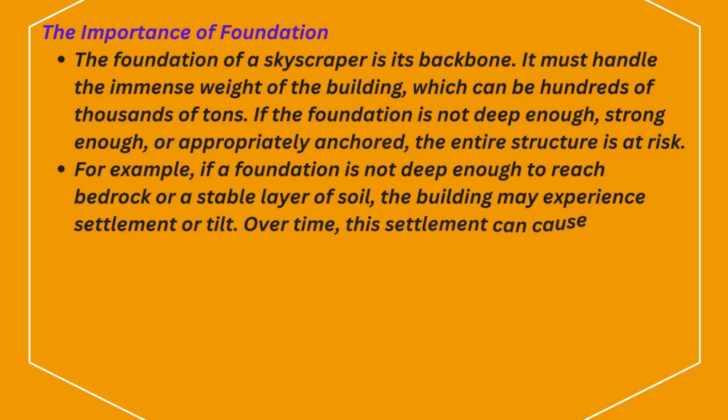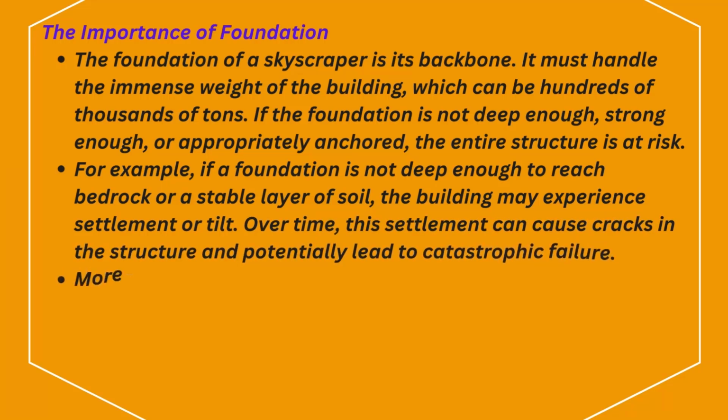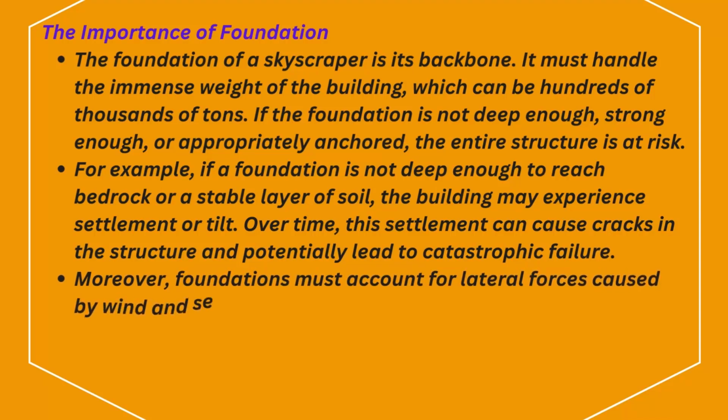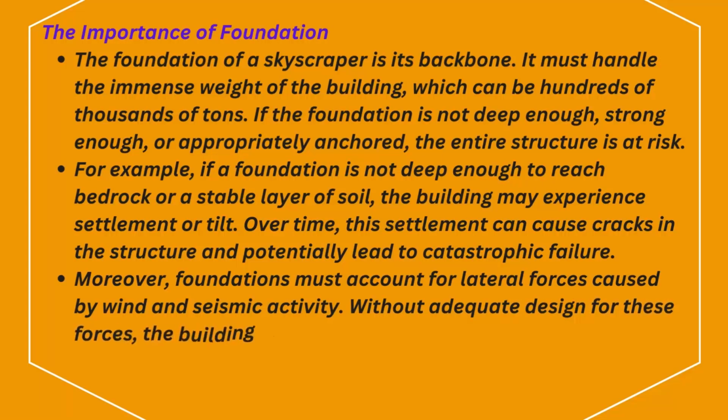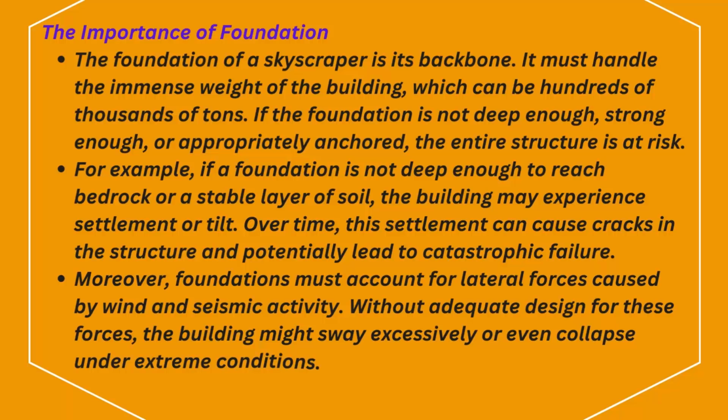Over time, this settlement can cause cracks in the structure and potentially lead to catastrophic failure. Moreover, foundations must account for lateral forces caused by wind and seismic activity. Without adequate design for these forces, the building might sway excessively or even collapse under extreme conditions.